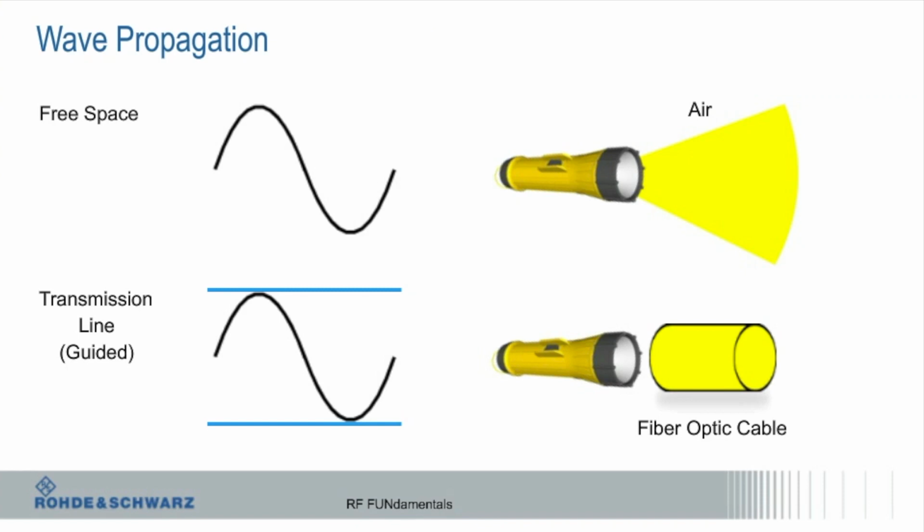So if you've done any kind of transmission line design, even like digital guys, you probably have had to make a 50 ohm line, or in some cases a 100 ohm differential pair, or there's some weird ones like 70 or 90 ohms, and I'll kind of mention that in a little bit, but transmission lines.